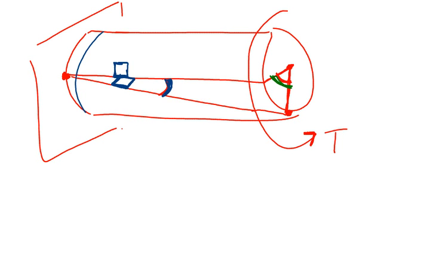So what is this angle? This angle corresponds to the change in the right angle of that square. And what do we define that as? That change in angle, we defined last time, if you remember, as the shear strain. The shear strain is simply the change in the right angle of the square after it gets deformed due to a shear stress. So this angle here is actually gamma. That's our shear strain.